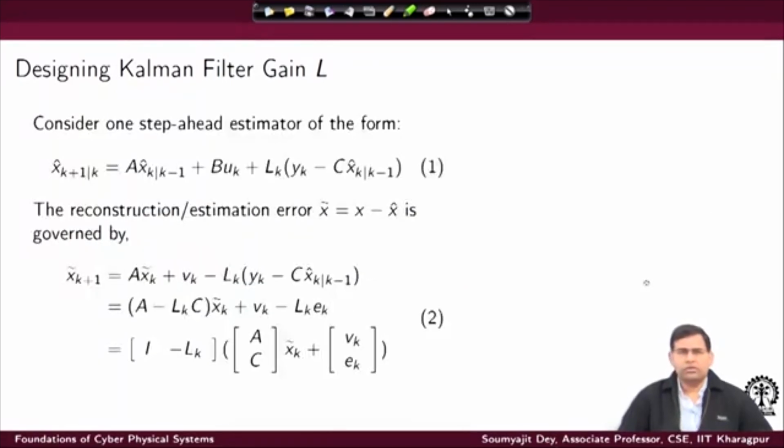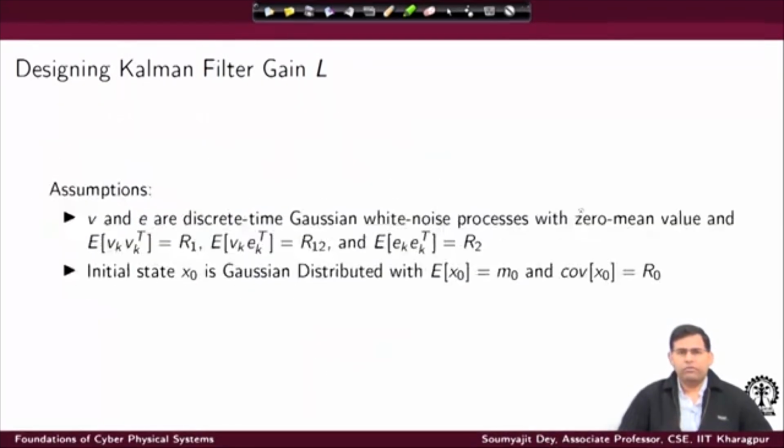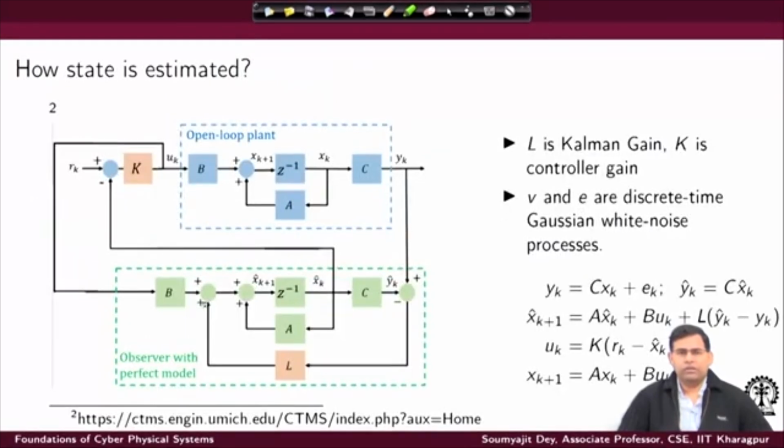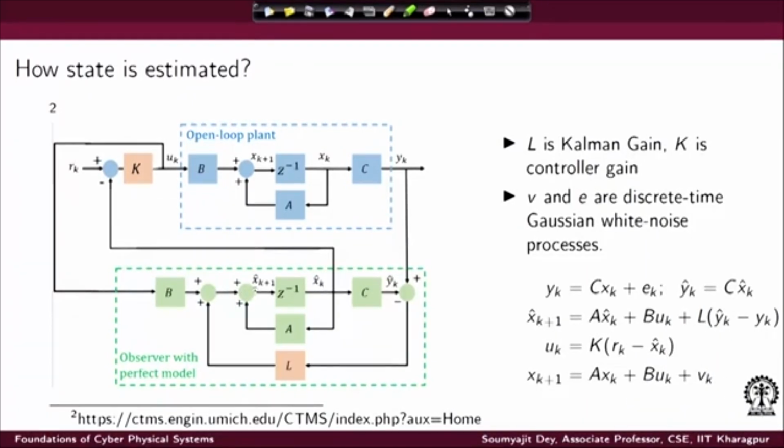Okay. So, overall, from this picture of actual deployment, that how the system is really going to work with an observer that is generating these estimates, I can write this update equation, right, because you see this is how I am able to generate x k plus 1's estimate using A x k hat, B u k, and I am expecting the Kalman gain to do a good job, so that it does try to minimize this difference.